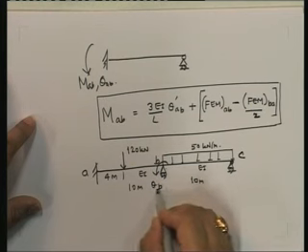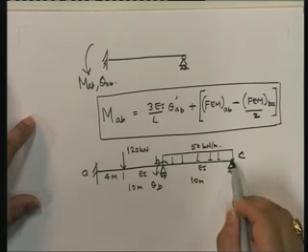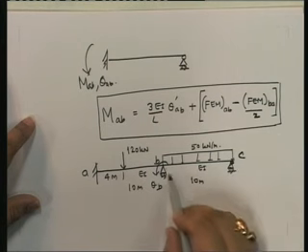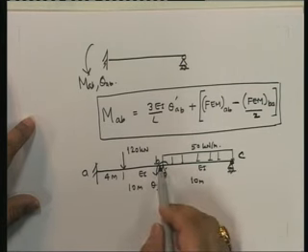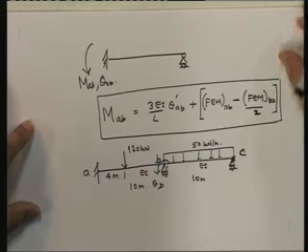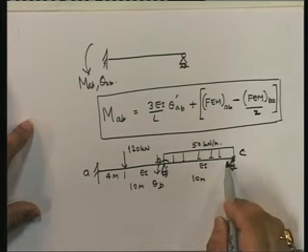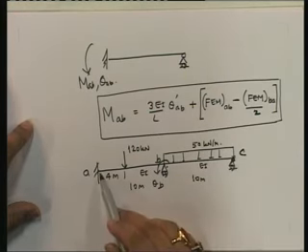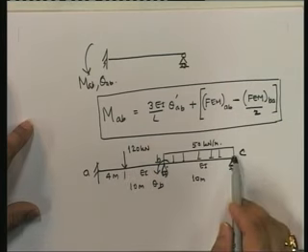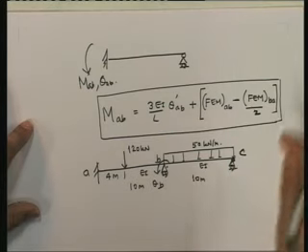So now, in this particular case, since I know that the moment is equal to 0 and I am not interested in knowing what the rotation over here is, what is the only degree of freedom that I have? Theta B. Because note that I am not interested in theta C, because I know that the moment over here is equal to 0. So I am going to use a modified, for the AB I am going to use the original element, and for BC I am going to use a modified element. Let's see what happens. So I am going to define this problem in a different way. Earlier what had we done? We had taken AB as fixed, BC as fixed, and we had defined theta B and theta C. Both of those unknown displacements.